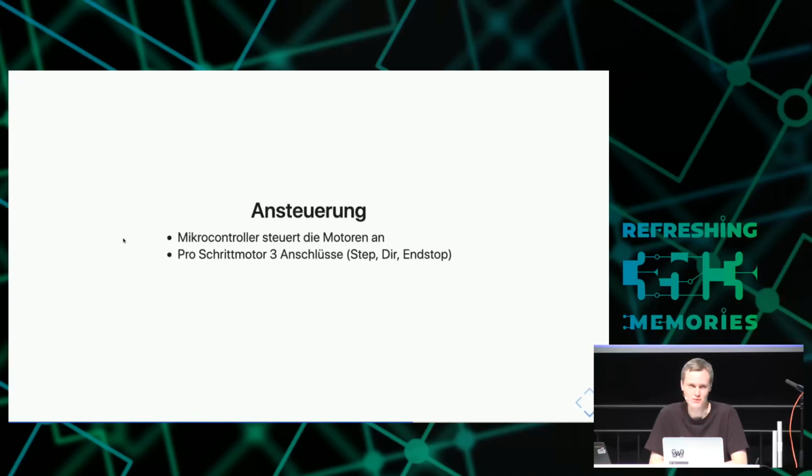Also, you would need an end stop switch, so that you know that you're at your final position or position 0, and the valve is completely open or closed. So you need 4 contacts, and there are controllers which can handle this. I have a TIVA board which has about 100 GPIOs, which you can use. So this is a good thing you can use to control organ pipes.